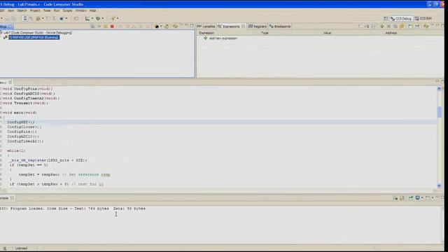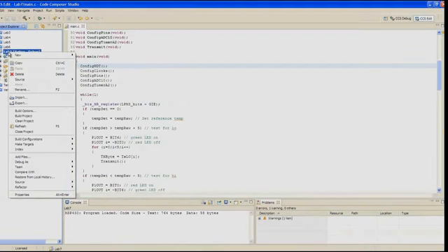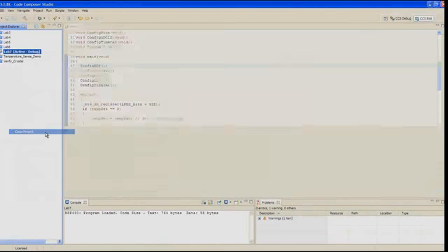When you're done, go ahead and close the terminal program. In step 24, terminate the active debug session using the terminate button. This will close the debugger and return CCS to the edit view. In step 25, go ahead and close the Lab 7 project in the Project Explorer pane. You're done.